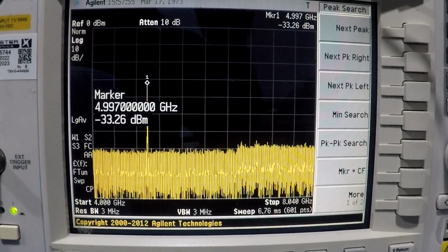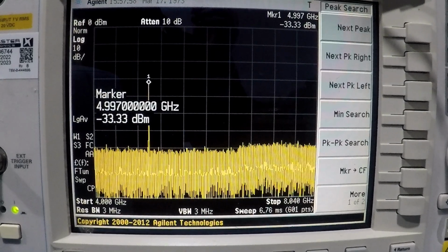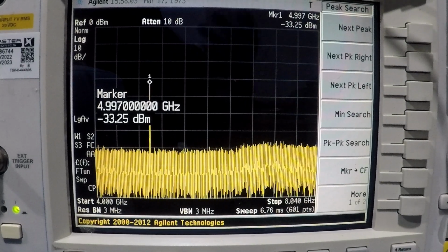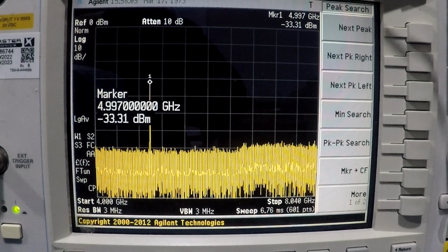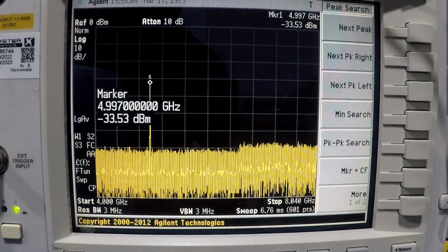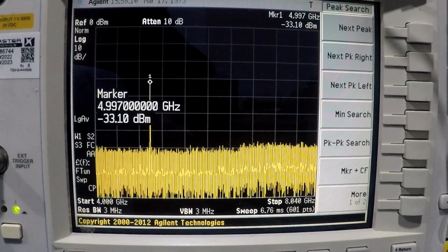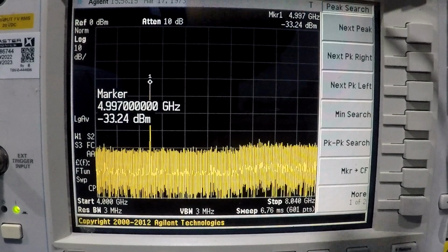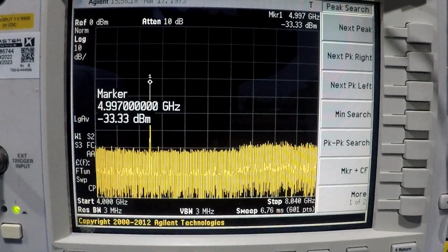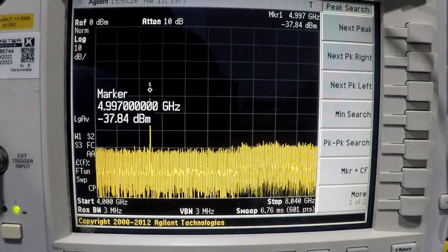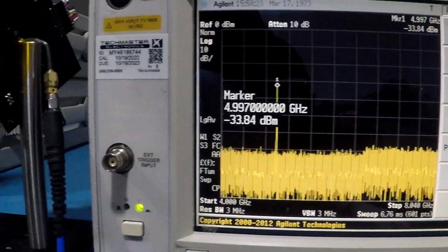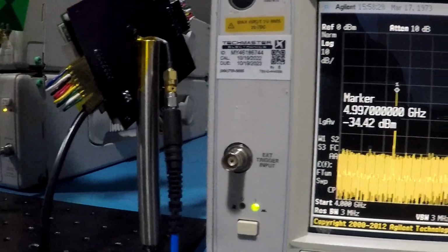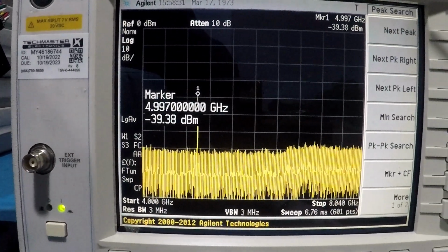So we have the antenna powered on. The AI's first data point is 5 gigahertz, so that's what it's set the smart antenna to, as well as the transmit antenna. For the first test, we're going to see what happens when we put in some interference. Right now I have some copper clad FR4, and if I get between the 2 antennas, we can see that nothing really happens.